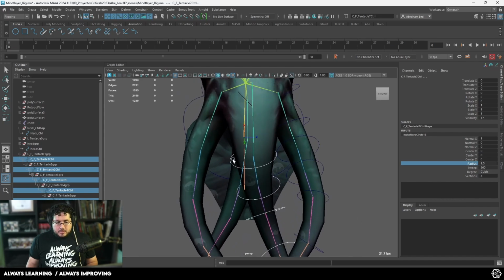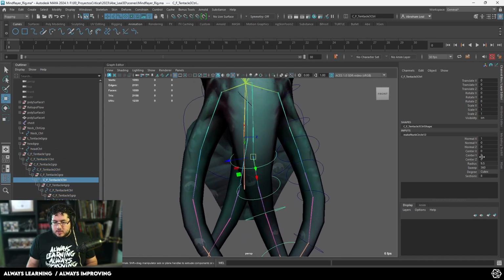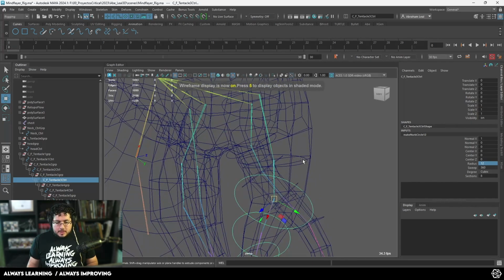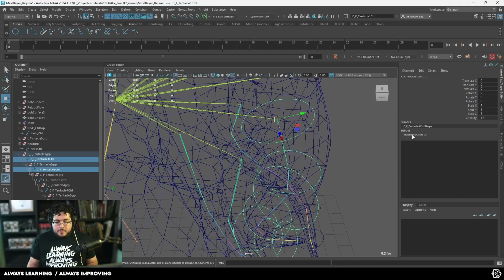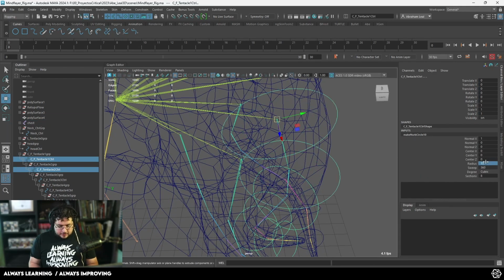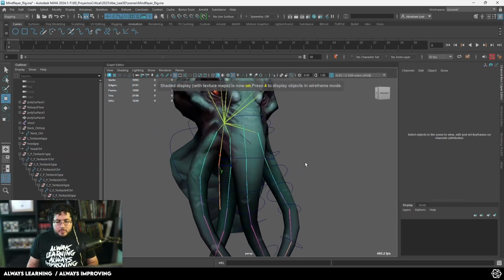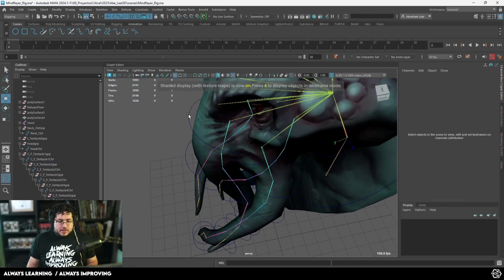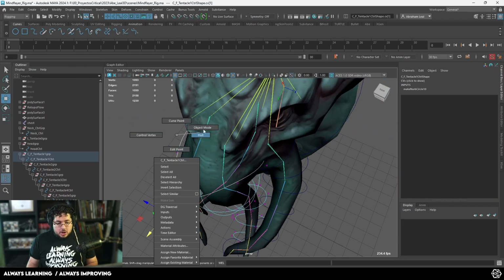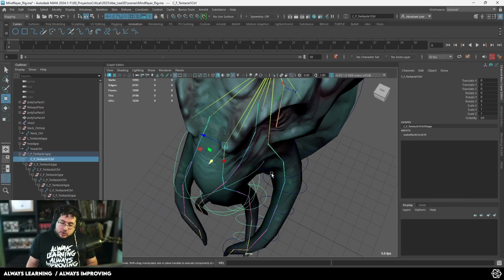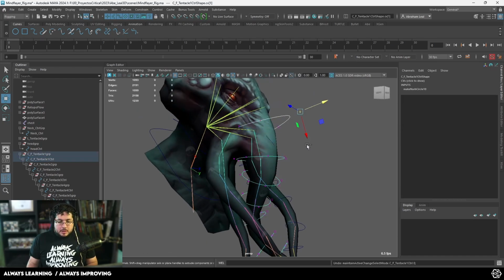So I'm going to go right around there, grab this one, and change the radius to like a 12, and then we got another one right here, and another one up here. This one I'm going to make like a 15 or something. So remember, if you want to modify the components, for instance, if you want to make this a little bit spikier, go to the control vertex. Do not scale the object. You always want the information of your curves to be completely clean.